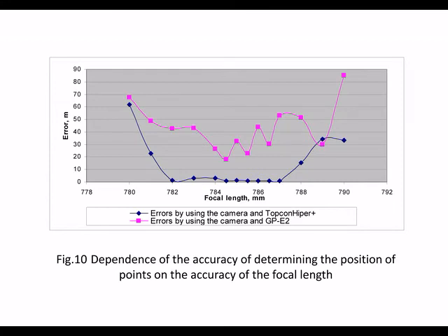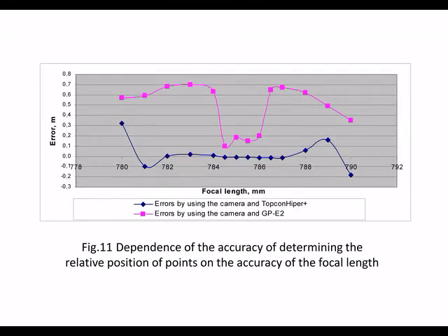The proposed method performs ground-based digital surveys with the coordination of photographing stations using a GPS receiver instead of them, making it possible to increase the efficiency of monitoring the deformations of objects located in dangerous zones of rock movement and the ground surface.